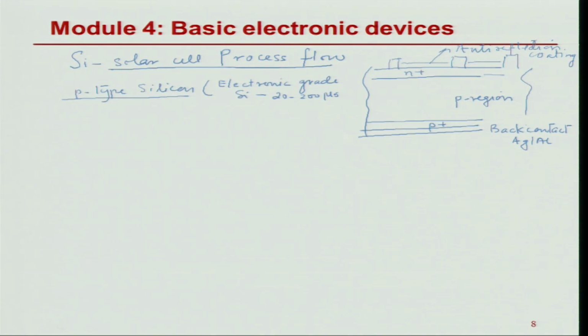So one can change that to a multicrystalline, it's called multicrystalline silicon, and one takes a hit on the efficiency and also on the minority carrier lifetime, which goes maybe in the range of 1 to 30 microseconds. And then there are other things which are coming up which reduce further the lifetime to some extent, but the cost reduction is much more, so that is still beneficial.